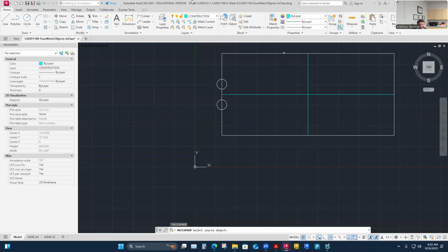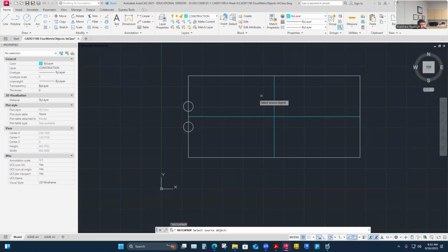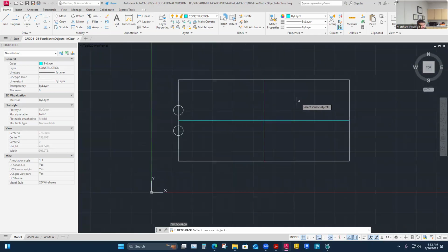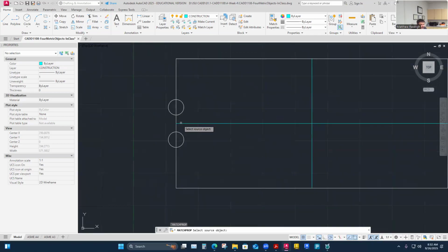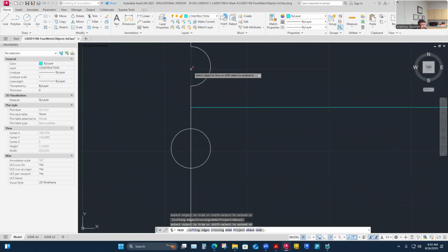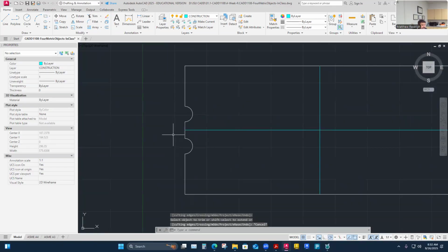These will have to be on a half scale, a 1 to 2 scale, to fit on that sheet. Because this is already 420 millimeters wide, so this is one of the bigger objects. It wouldn't fit on that without being half scaled. So I'm going to trim this up a little bit. These features really are just radius features, slots there.